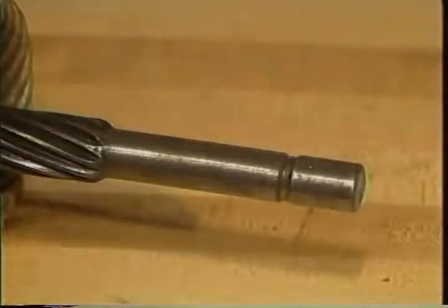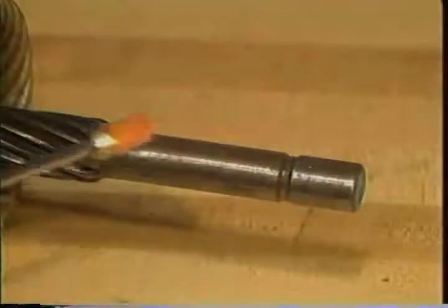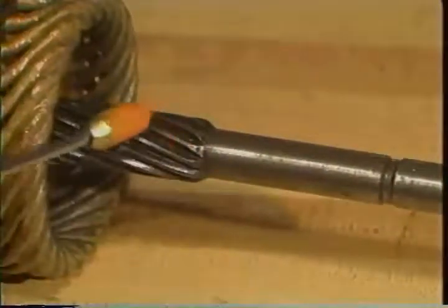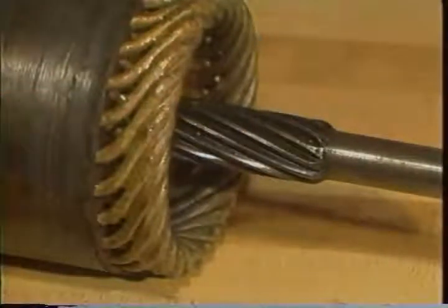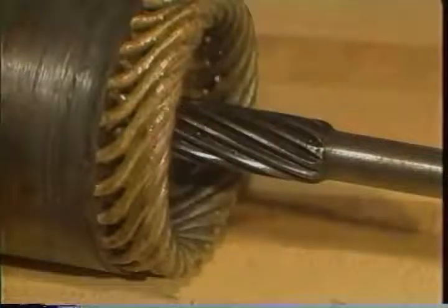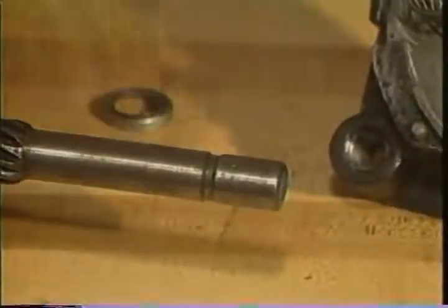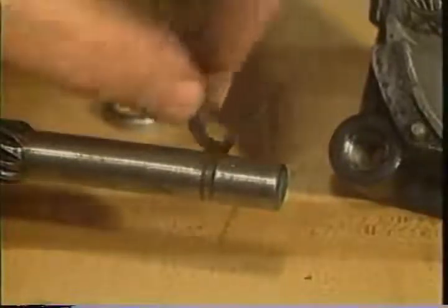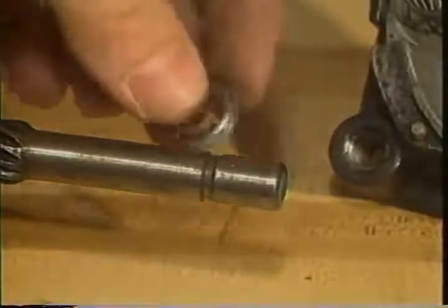On the other end of the armature shaft, note that a groove is machined for a snap ring. Spiral splines on the shaft are used to make the pinion gear and clutch turn with the shaft, but they allow the gear to slide back and forth. Some starters have a thick C-clip type snap ring like this one to secure the pinion gear assembly. A cup type washer fits over the C-clip to protect it.